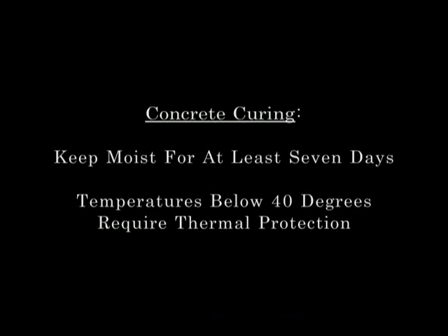Anytime you can shade the slab from direct sun is a good opportunity as well. If the temperature is going to drop below 40 degrees, you need to do some sort of thermal insulation. Again, the use of straw with plastic on top is a good way to achieve this. If you're going to be doing more than one slab and you anticipate having temperatures below 40 degrees more than once, then you might want to invest in thermal blankets. These are actually designed specifically to keep the heat in as the concrete cures. In terms of keeping the heat in, the concrete will produce its own heat as it's curing through the chemical process of hydration.